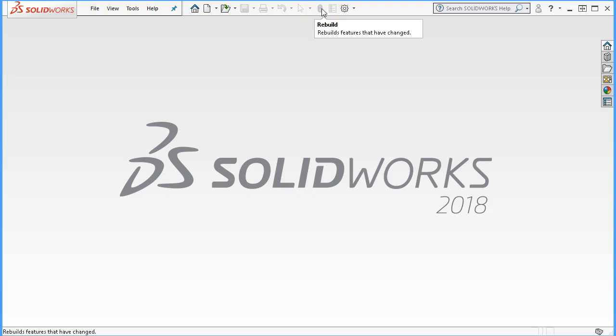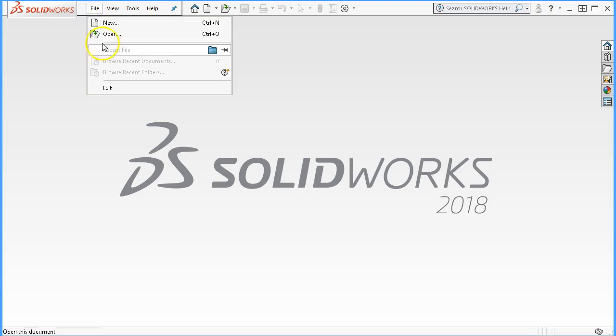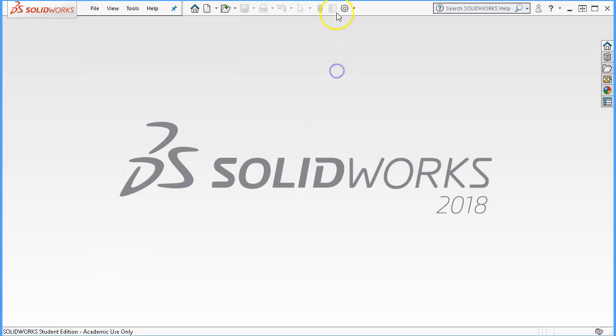Rebuild, and that should be a Control B, and we'll talk about the difference between Control B and Control Q. File properties is a shortcut to file, and I don't have a document open, so somewhere down here would be file properties, and that would also be why it's grayed out.